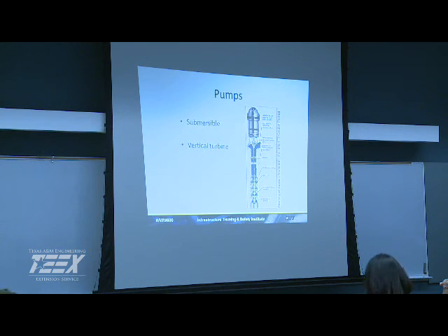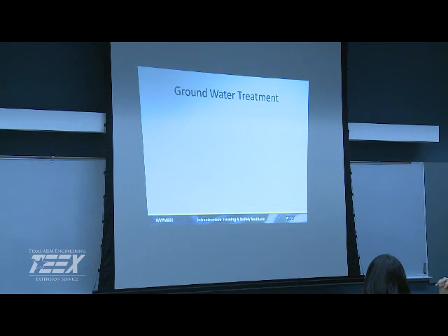So we have our submersible, which is down below and water cooled. A vertical shaft is going to be air cooled and have oil in it. Then we look at our series of pumps. Remember, anything that's oil lubed has to be NSF approved. Real important. If we do have issues with gases in our water, the easy way to get rid of them is aeration. We might have to do some corrosion control.